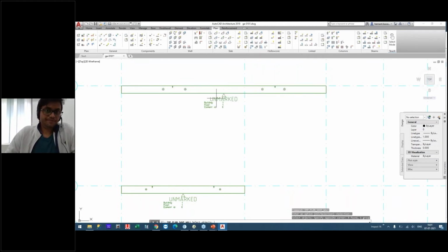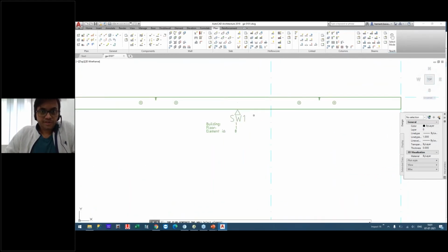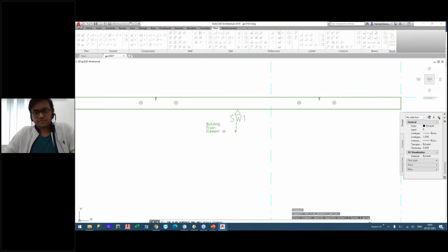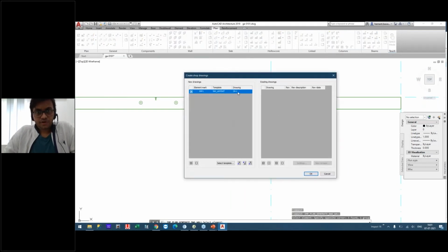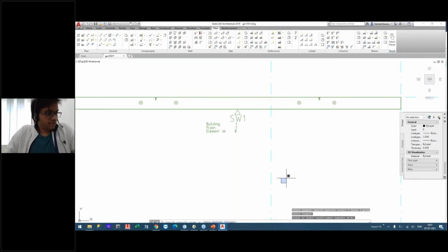and we'll create a shop drawing. We give the designation SW1, so it by default took SW1 as the prefix, and when we create the shop drawing for this one, SW1, the drawing name will be SW34-1 because we gave the prefix for drawings as 34- in our definitions. So I'll just start preparing a drawing. It will take maybe a minute or two. After this, if possible, we will also look into the MEP keys.